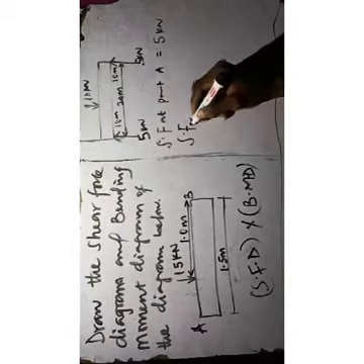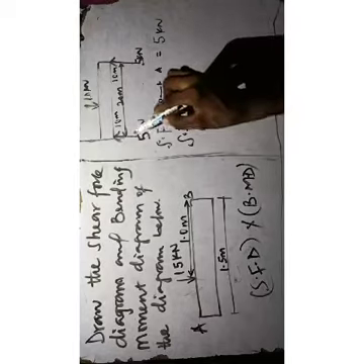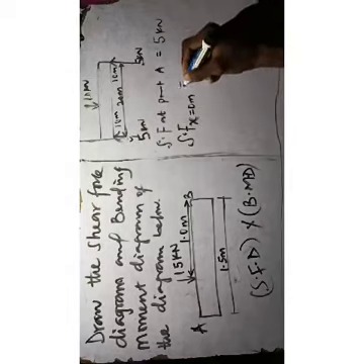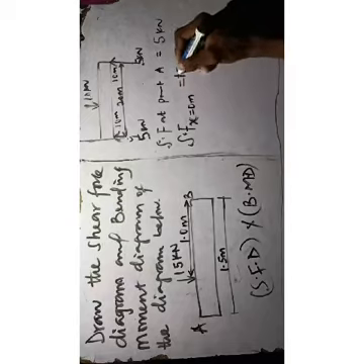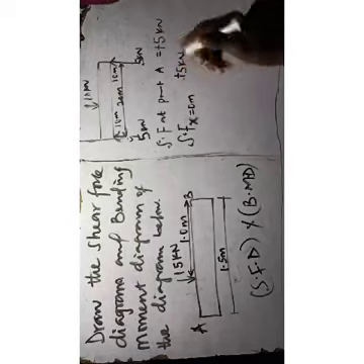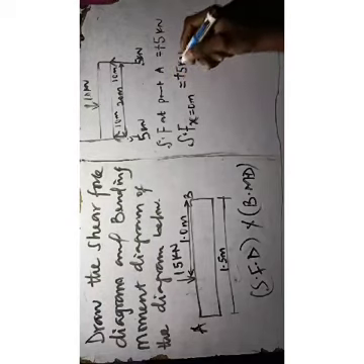Now you can write this as shear force at x, let's take the distance as x equal to 0 meter. Okay, sorry, this is just an abbreviation, the way you can write it. So this is shear force at x equal to 0 meter, and the shear force here you have as what? 5. That is plus, don't forget, put your sign, plus 5 kilonewton. It is very important to put the positive sign because sometimes you might have the negative part there as well.